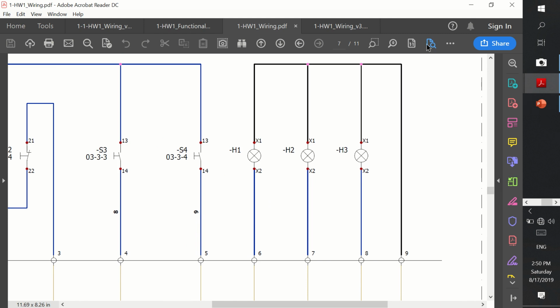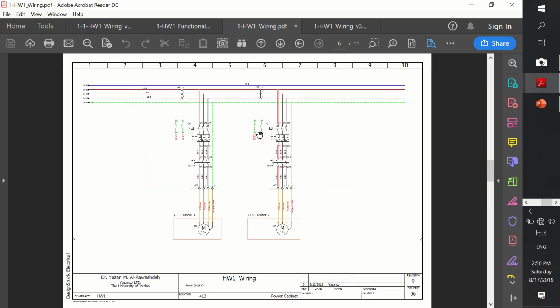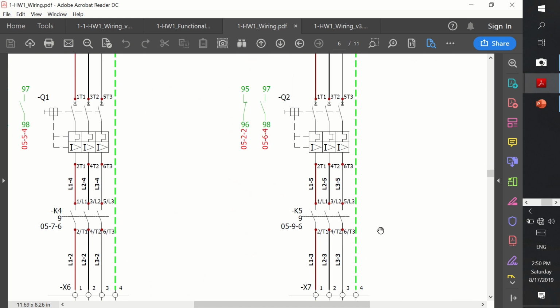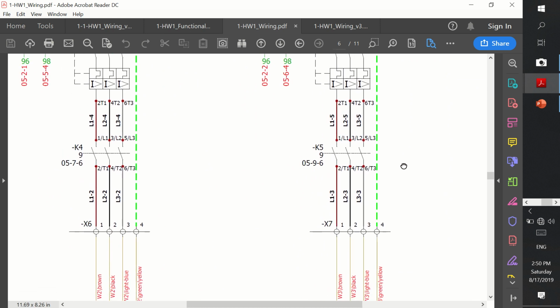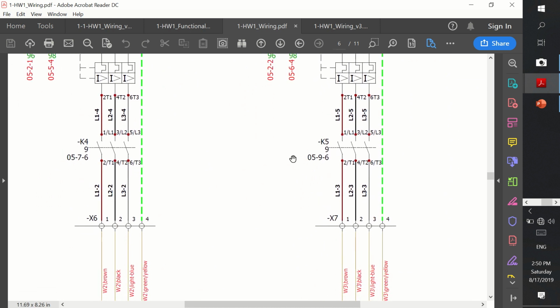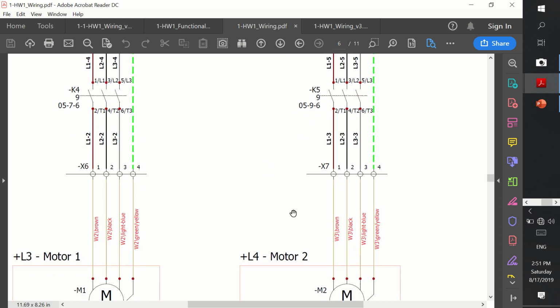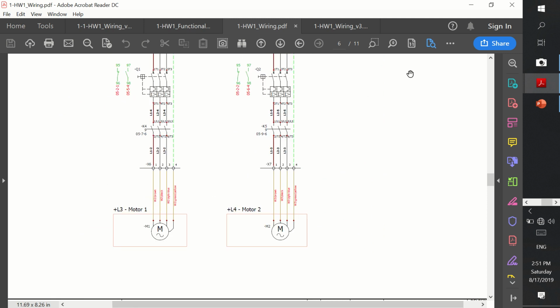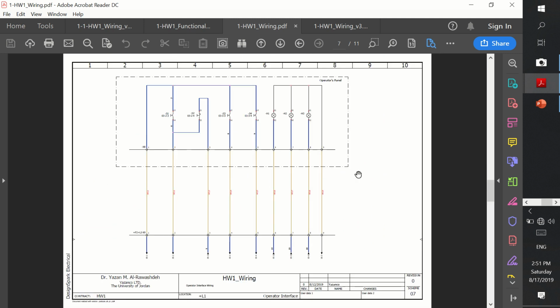So reading back to the power terminals, here I have assigned the power contactor manufacturer footprint, and the information available, and actually the software will automatically generate the terminal tags and marks so that I can speed up the wiring process and reduce the mistakes that might arise.